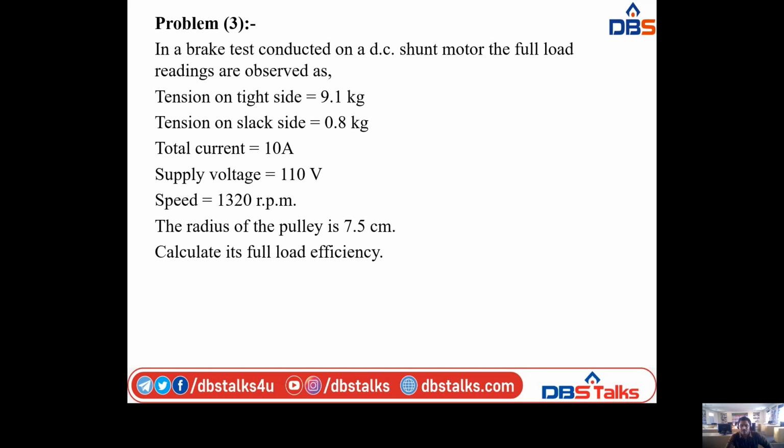So already we calculated the total loss, that is 3480 minus total copper loss 2249.6, and that is equal to 1230.4 watts. And stray losses for each machine, I already calculated this in the previous problem also, that is total stray loss by 2. Here the total stray loss is 1230.4 divided by 2, and finally we have the stray loss for each machine is 615.2 watts.